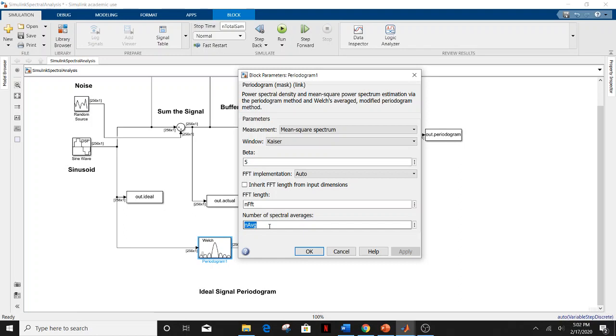It's going to find the magnitude of them and square it to get the power, and once it has that, it's going to divide by the number of frames that we're using. So you're going to get an average, basically power spectrum of your data. And again, the FFT length is going to be the number of FFT points that I want in my calculation. So for each frame, we're generating this number of points, and we'll be computing this length FFT.